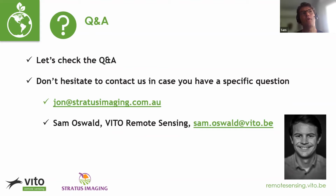In the case of multispectral cameras, what we do is use things like sun sensors and calibration pads. These are able to calculate the different lighting conditions which might affect the output result and account for them. In the case of RGB imagery, this isn't so useful, but also in the case of RGB imagery, normally you aren't so interested in the lighting.